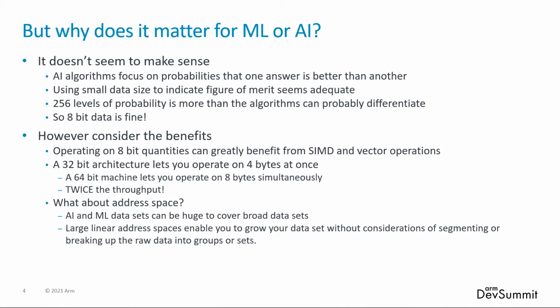And this does not even take into account the fact that many 64-bit processors will also have vector accelerators that can operate on 128 or 256 bits at a time. These could represent SIMD operations on up to 16 or 32 bytes at a single time, again multiplying your throughput by another factor of 2 or 4 over the 64-bit core register operations.